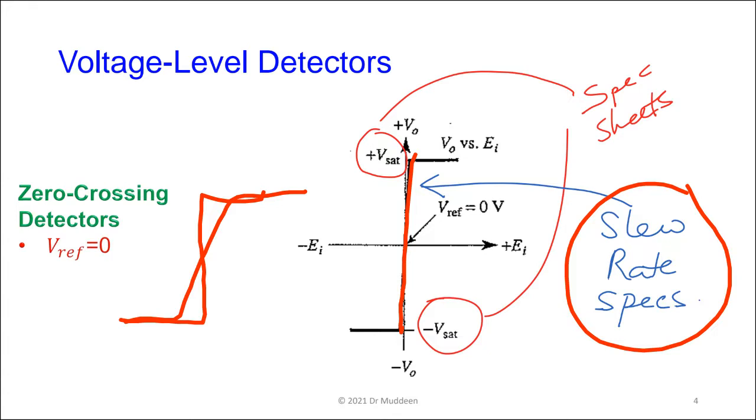And again, the better the thing is designed, the more expensive it is, because it costs money to compensate for these capacitances and the like. The closer to an ideal performance you're going to get. If you need that kind of thing, and this is for design work and so on, you have to go back to the spec sheets. They give you things like the slew rate, they give you things like the VSAT, the V-saturation levels. So it always is back to that.